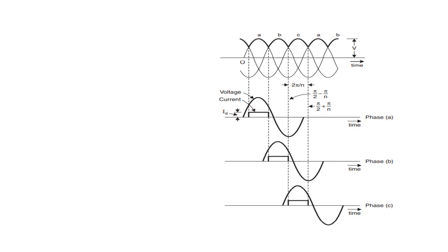Three-phase HVDC transmission uses a three pulse converter or six pulse converter, and generally it uses a 12 pulse converter, but these are the base converters that are used for a 12 pulse converter. Okay, so I'm generalizing it as n pulse, where n refers to the number of pulses. For a three pulse converter, these are your phase voltages, VAO, VBO, VCO.